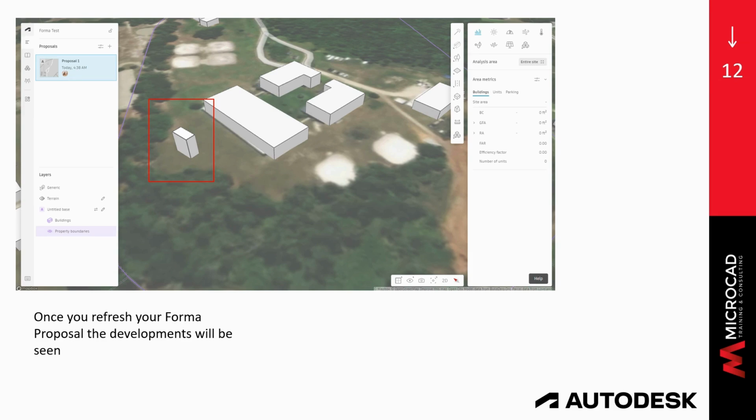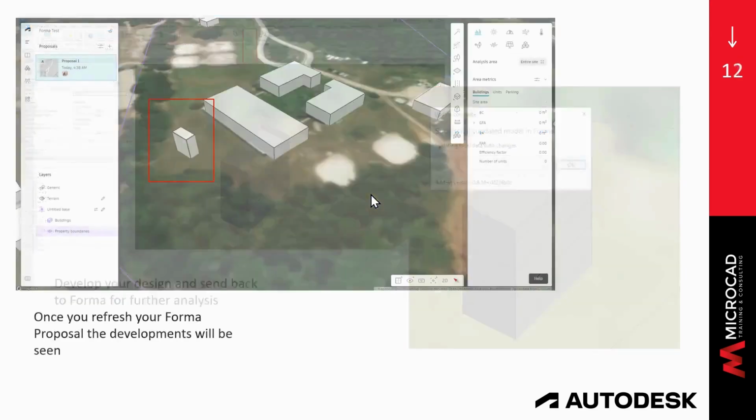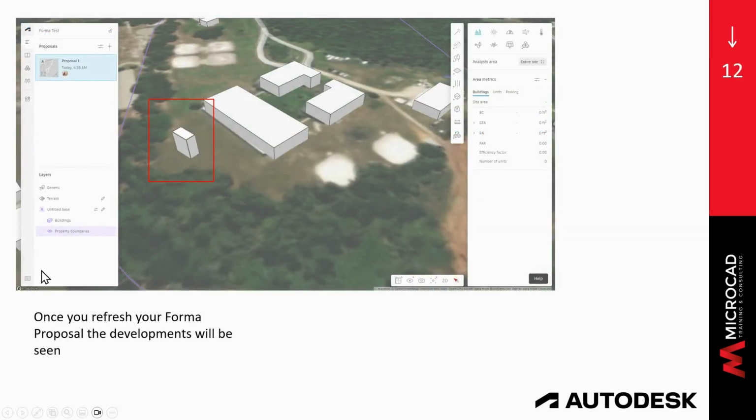Now, something that I would like to bring to your attention, it is going to be important when working between Forma and Revit. Now, from Revit to Forma, I can make as many updates as I want, right? So for example, I go back to this building, right, and add an extension and add a secondary building, and I extend the elevation. I make the building higher, right? I can send the update, right? So everything is going to go right here, straight to the building.